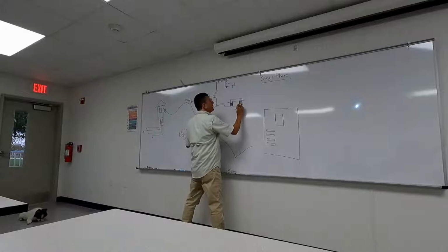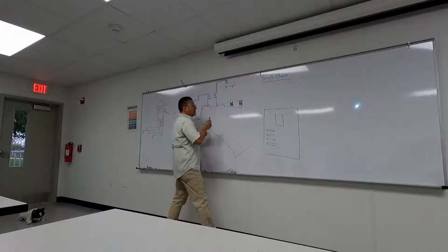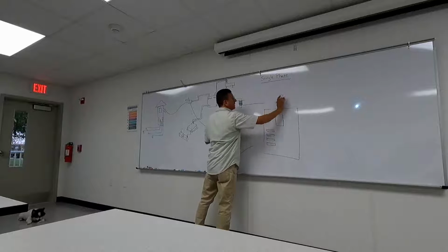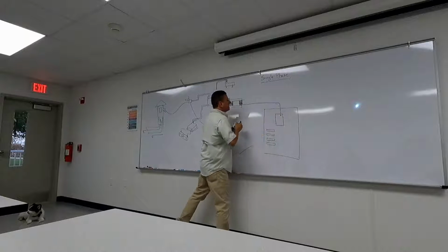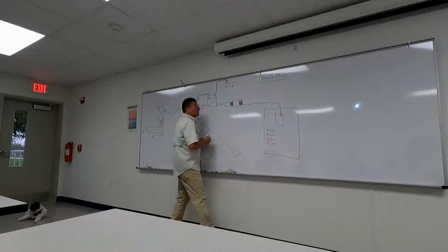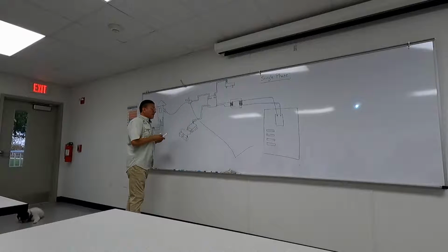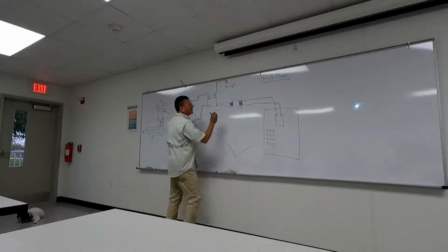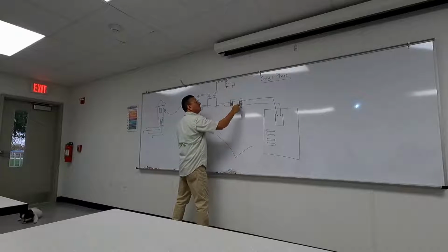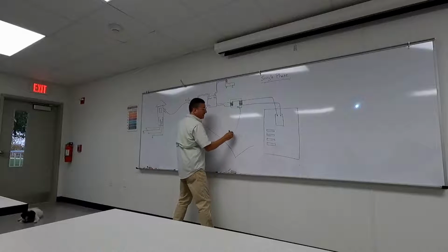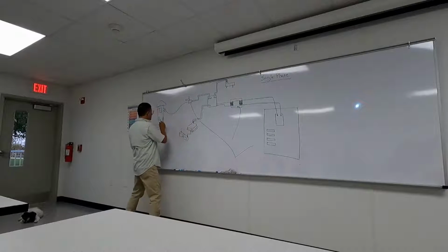Because this isolation transformer, what happened with the amount of coils? The amount of turns? They are the same, no? It's only to clean. And what about the ground here? Look at this. The ground is any part of the frame. The frame is iron. In other words, the neutral and ground are together.